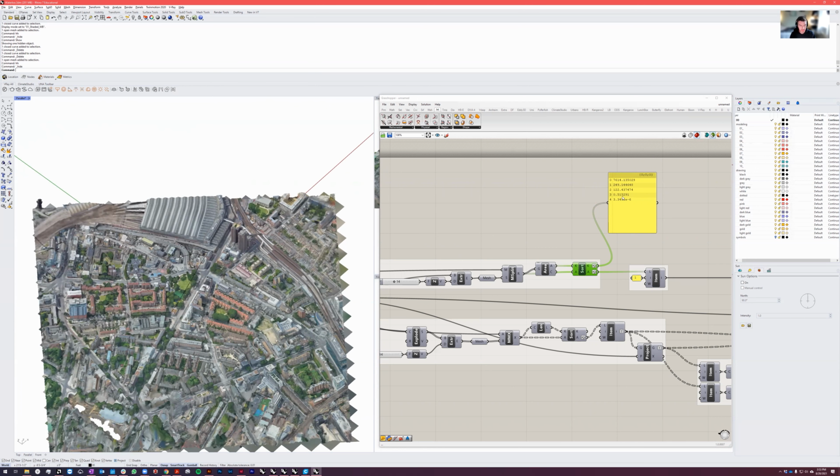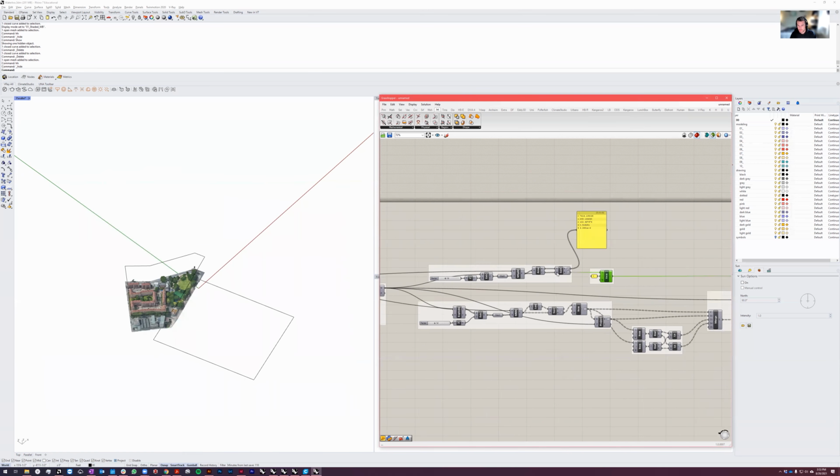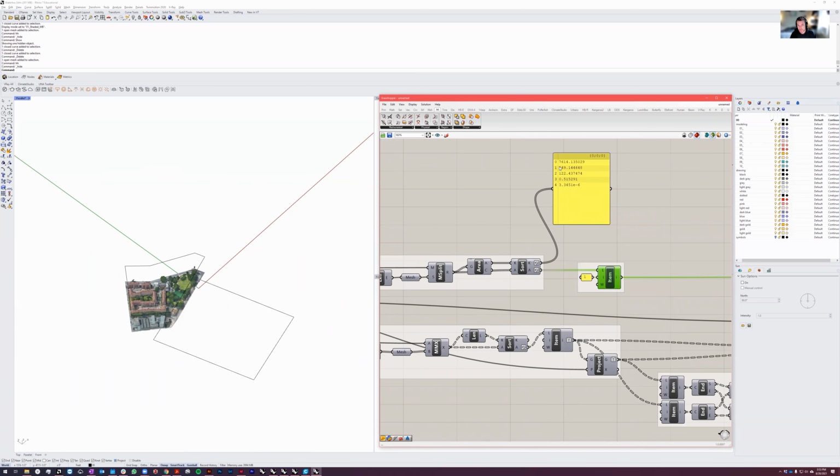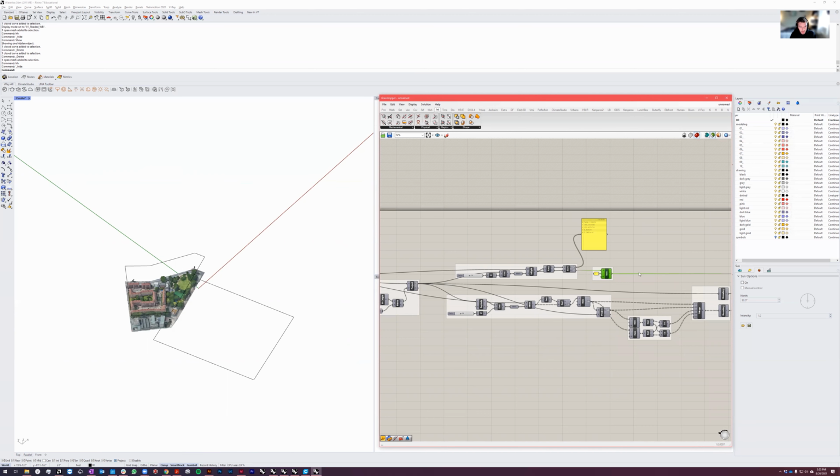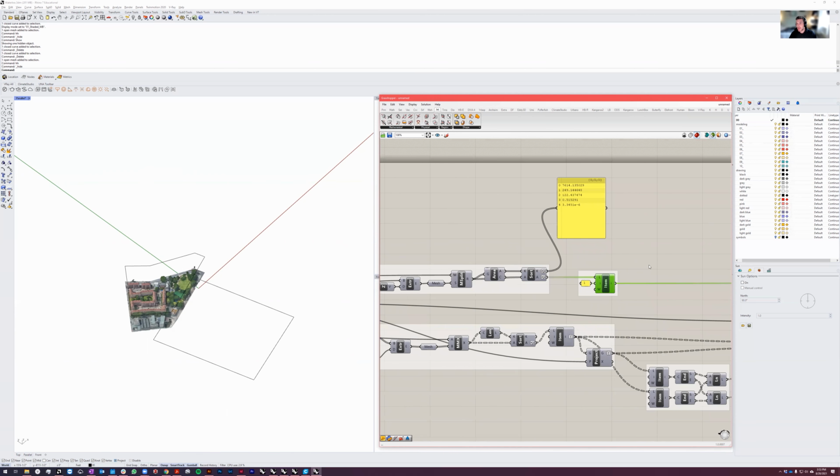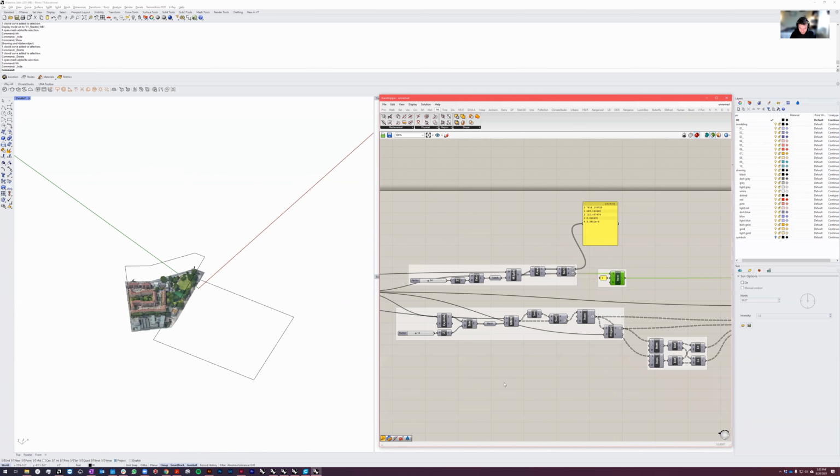And then you have these really, really small ones, because I think we're probably splitting a tiny random floating mesh somewhere into two. So I know I don't want the outside one, I want the inside one. We know that the inside one is going to be the one that has the second largest area. So I'm selecting that, you can see item number one here. So that's good. Now I have the mesh trimmed and constrained.